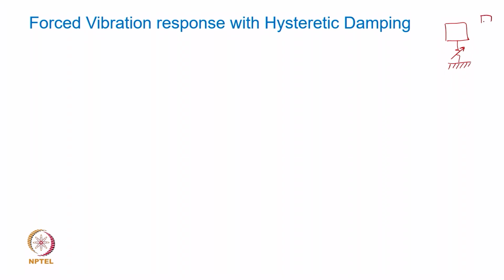We discussed that it can be both stiffness and damping property in one single structural element, that is the engine mount or any rubber isolator, polymeric isolator, or even a simple structure, let us say an I-beam or whatever is the material. So, the only difference in this case we have discussed is that it has a complex stiffness. You remember K was actually a complex stiffness.